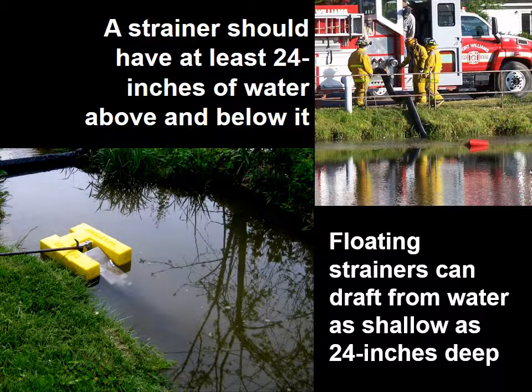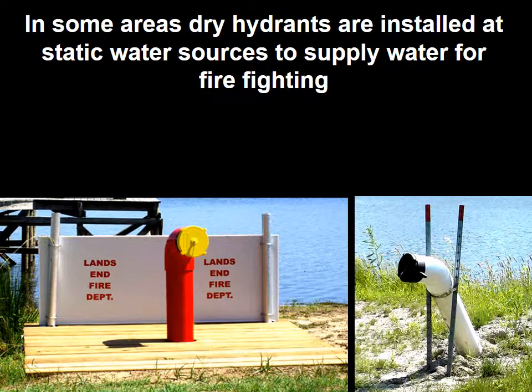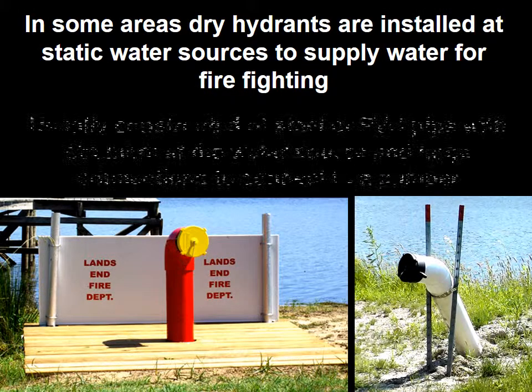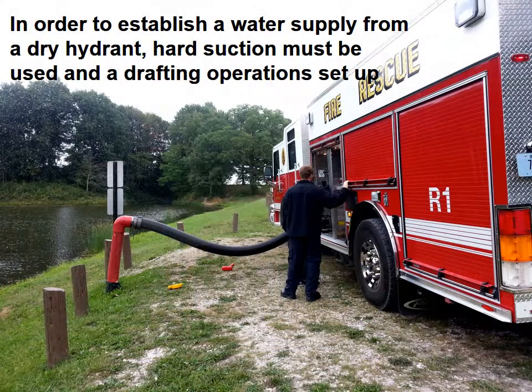In some areas, dry hydrants are installed at static water sources to supply water for firefighting. These dry hydrants are usually constructed of steel or PVC pipe with strainers at the water source and large connections to connect the pumper to. In order to establish a water supply from a dry hydrant, hard suction must be used in a drafting operation setup.